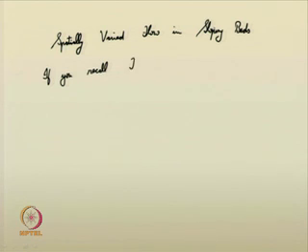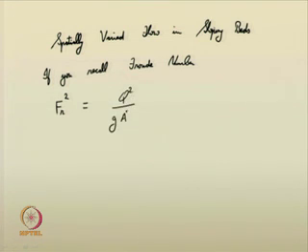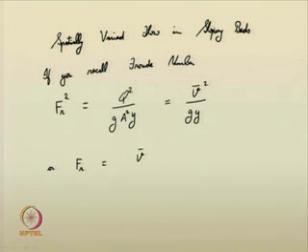If you recall the Froude number, we had suggested that Froude number is equal to Q squared by g A squared y, or this is equal to v squared by g y, or sometimes we may write Froude number Fr is equal to v by root of g y.